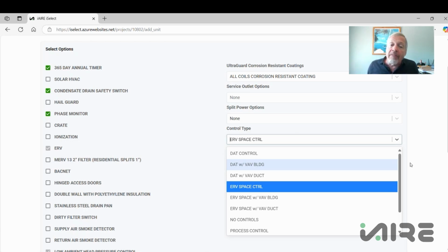So if I've got return air coming back into unit B, right, and I'm mixing outside air with it, that outside air has to be processed. So by creating neutral conditions, the same temperature and humidity of the air coming back, now I can mix those air streams within that package unit and not cause any problems. I won't cause moisture to grow. I won't cause mold to grow, any of that sort of thing, because my two convergent air streams are the same temperature and humidity conditions. That is application number one for discharge air control.